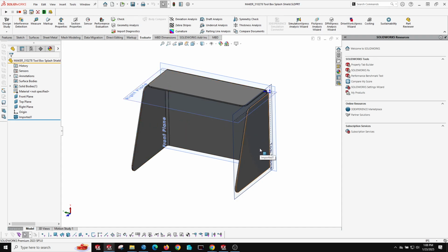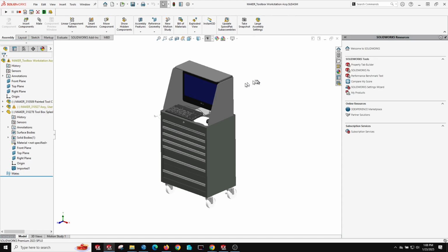Again, I don't have the feature history, but depending upon the part, the complexity of its geometry, I certainly can use the FeatureWorks recognition tool to bring these back to being fully parametric editable models. So again, that is workflow one. I've got a file, or a set of files actually, that is capable of being opened by a commercial or an academic or student version of SOLIDWORKS.